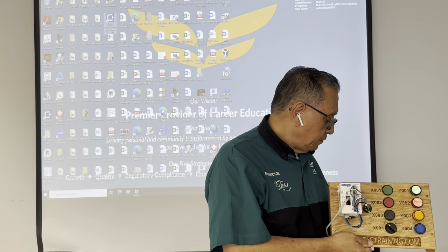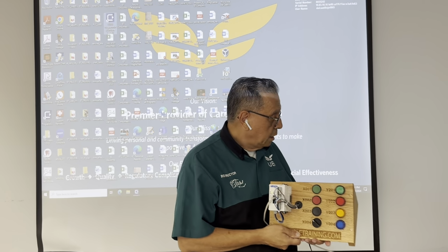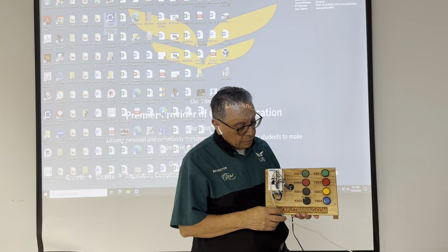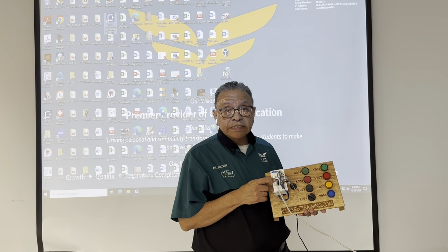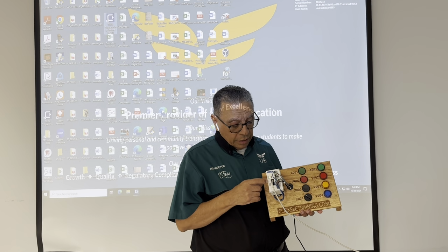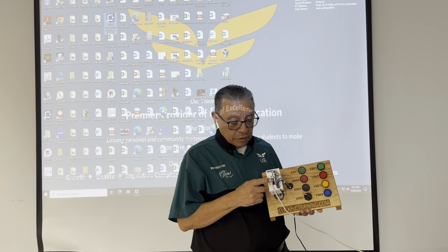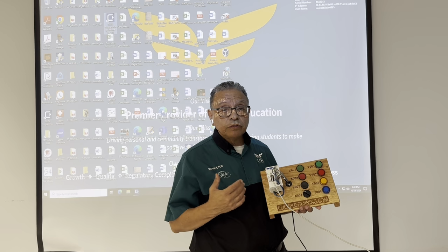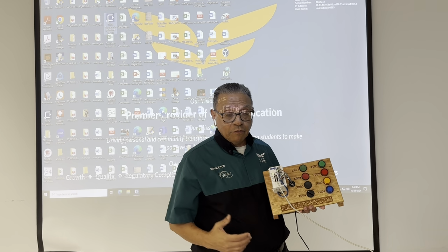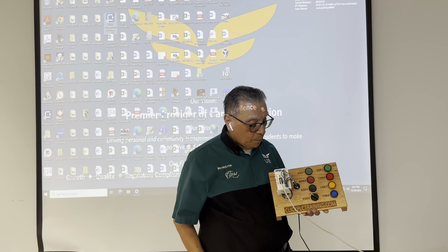So this is my PLC CPU. Also, it has a communication port, a serial port, that is used to get connected to the computer. This cable, in the middle of the cable, we have a USB interface that connects the communication port, COM1 or 2 or 3 or 4, depending on which one we are using on a specific computer, with the USB port.